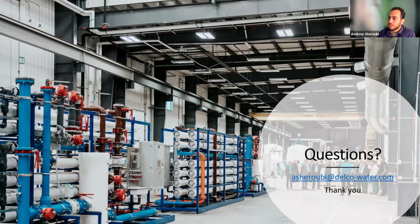There's also a technology out there called biofiltration, which is biofiltration for groundwater. It's different from what you've seen for wastewater, where you get bacteria that oxidize iron and manganese. When they oxidize them, they take them out of solution. And if you have higher iron, when the iron-oxidizing bacteria oxidize it, the arsenic co-precipitates out with the iron. So you could use the biofilters without any chemical addition to remove arsenic. But that is a less reliable method than the other two.